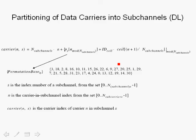A few more important points about the permutation and the partitioning of data carriers into the subchannels. The fact that the ID cell enters in this permutation is very important because when you have a multi-cell situation where multiple base stations are serving subscriber stations, and subscriber stations could be close to each other between the cells, then by using different IDs for the cell, the probability that the adjacent subchannels and cells will actually coincide is low.